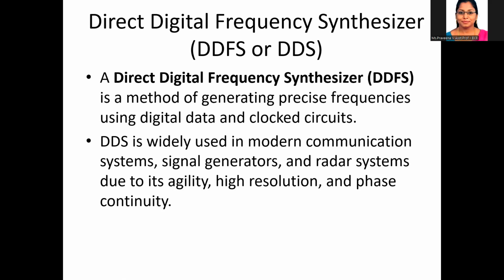Unlike a PLL based synthesizer, such as the integer-N frequency synthesizer, DDFS creates the frequencies directly in digital form. It offers very fine frequency resolution and extremely fast switching between frequencies.